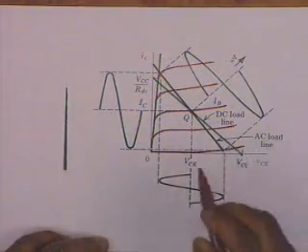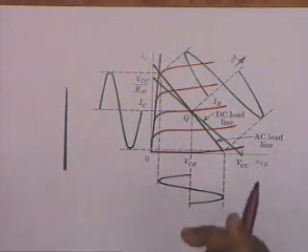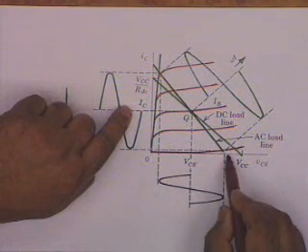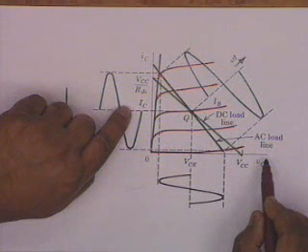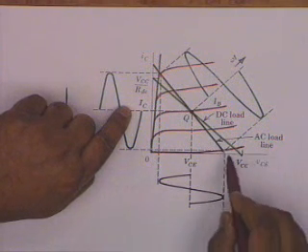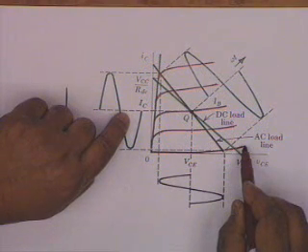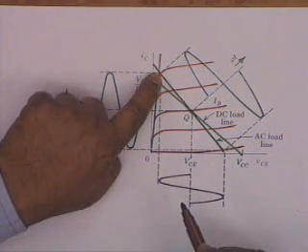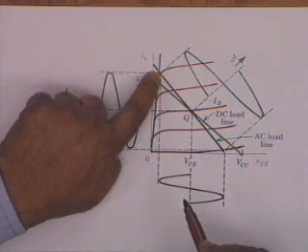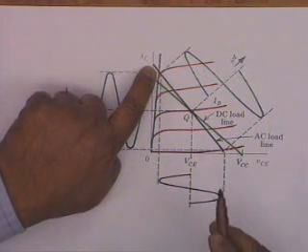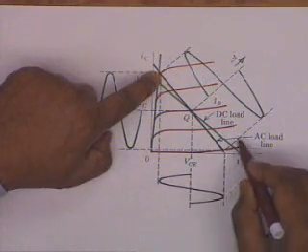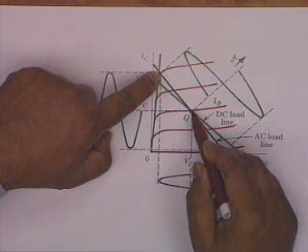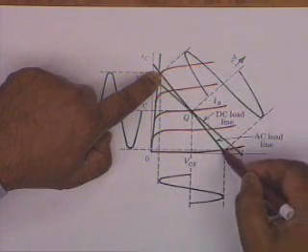Now, when it does so, then obviously for power amplifier operation, you must restrict it between this point. You see, it doesn't go right up to the VCE axis. Why not? Because you cannot go below IB equal to 0. It must end here. Similarly, it cannot exceed this point, because then it will go into the non-linear region of the characteristic, and therefore your operation is restricted between this point and this point. This is the Q point, and your operation is restricted between this point and this point.